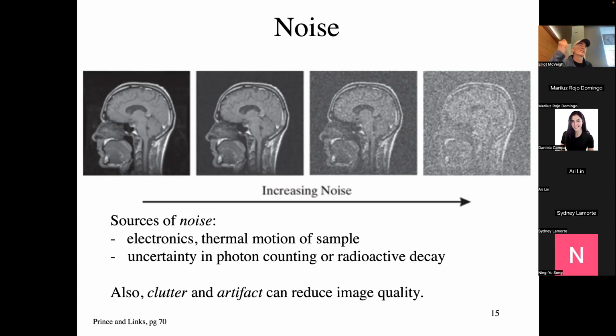If I take a radio frequency coil tuned to the right frequency, actually even if it's not tuned to the right frequency, and I hold it up to the patient and look at my scope, I will see the noise go up when I put it next to the patient. When I take it back out in space, that noise goes down. So it's the thermal agitation of the charged particles in the patient that is causing the noise in this coil, right? That is something that's always going to be there. We need to make a signal that is higher than that background noise.